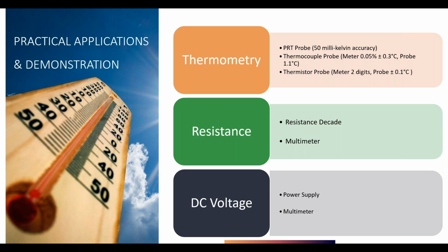You've got, let's say, a Fluke 87. Anybody venture a guess on the temperature accuracy of a Fluke 87 multimeter? I mean, its primary function isn't necessarily temperature measurement. Yes, it has the little yellow thermometer on it, and yes, you could put it into temperature mode. But again, just because something reads temperature doesn't mean that it's the right tool for the job, right? So you've got about 1.5 degrees accuracy on that Fluke 87 before you even plug a probe into it. So let's say you plug the same thermocouple probe into the Fluke 87. You now have a 3 degree swing on a Fluke 87.